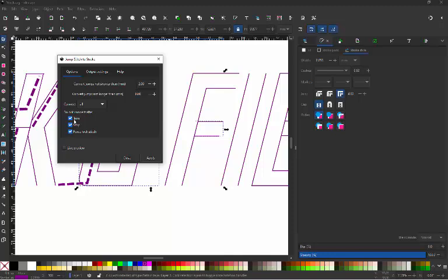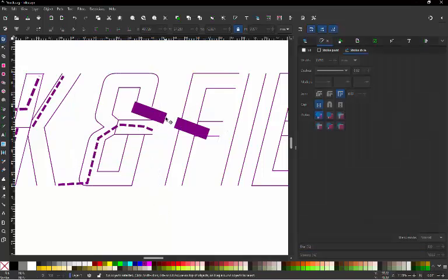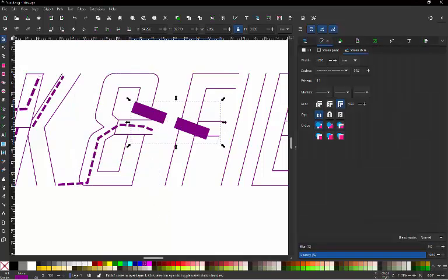And notice that it says do not connect after a trim. So we could have turned that off, and even though we had a trim command assigned, it would have still made the connection. But I have those options selected so that I know to go and turn off my trim command. Otherwise, we're not going to know that there was a trim command applied in params. So it's a bit of a give and take there. But that's just how I like to do it.